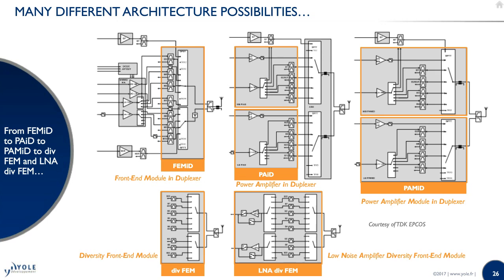Do you integrate the filters, or what we call the duplexers? Duplexers are just two filters where you isolate the reception from the transmission, okay? So from duplexers, we move into quadplexers even, depending on how many carriers we are using to send the information: at the beginning 2 carriers, then 3, 4 carriers possible today. So you could see triplexers, quadplexers even.